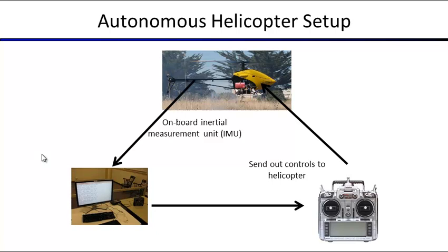Then on board you have inertial sensors, so accelerometers, gyros, and magnetometers. That data gets sent down. Then to know the position of your helicopter, you can put a GPS on there, but the problem with GPS is that it works with an antenna that has to look at the satellites. If the antenna is not seeing the satellites, then it's not going to know where it is. And even when it sees the satellites, it takes a few seconds at least to lock onto the signal.